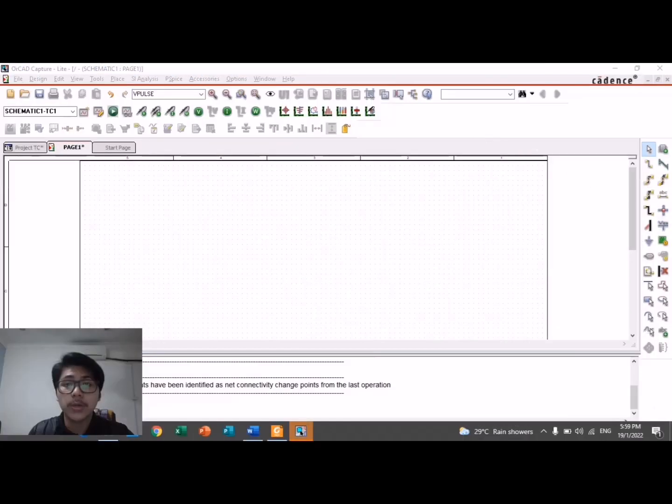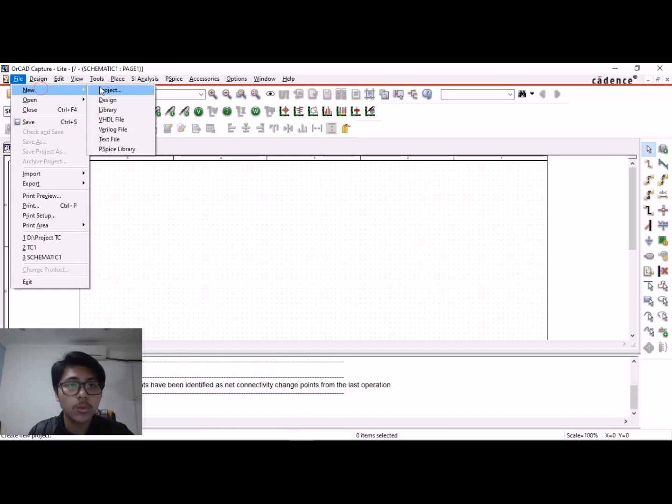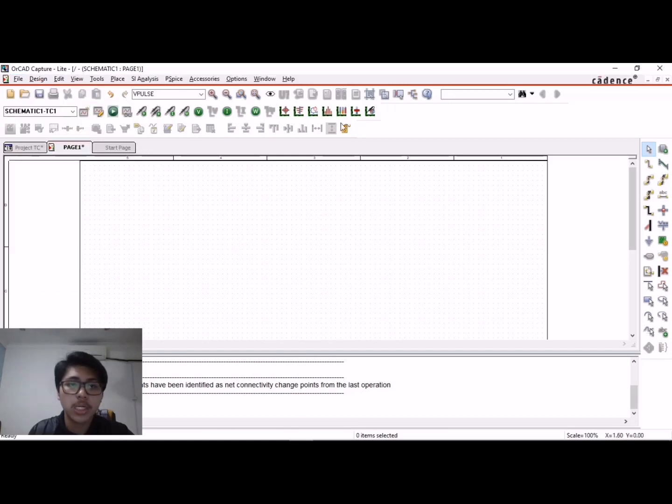Assalamualaikum, my name is M. Rifqi Aiman bin Azizan. My matric number is DE200115. I'm from group 7. We will present how to do a simulation for our group project, which is non-sinusoidal AC input signal for RLC by using PSpice. Firstly, you need to open OrCAD Capture, which is the PSpice. Then click File, click New, and click Project. Then your screen will appear like this, which is the canvas.